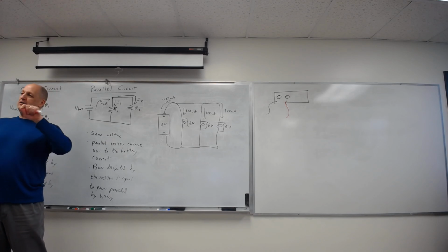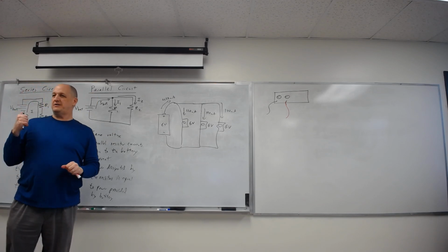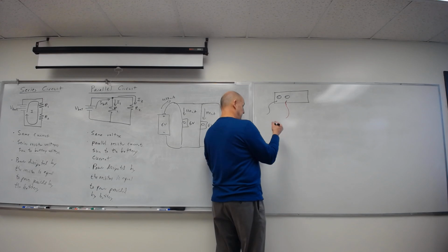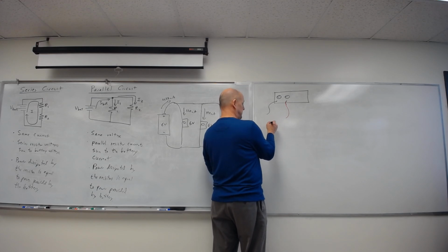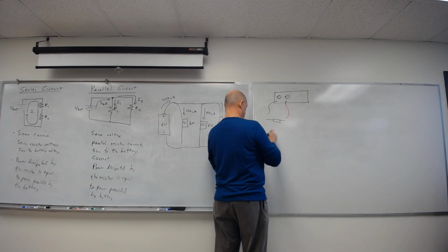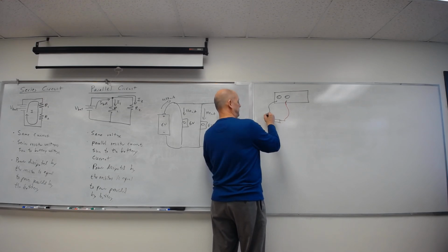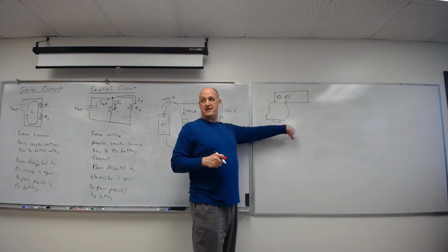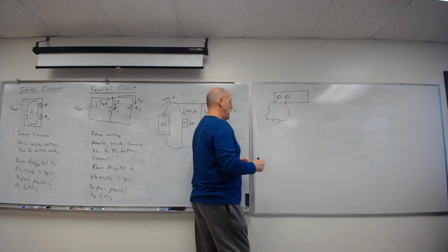Don't connect power through my ammeter directly to the ground to measure the current. You have to have the resistor in there. So if I want to come down and do a single resistor, the first part, I just put that resistor in here initially and connect it. So I have a circuit. It's my brown, black, red resistor, 1 kilo ohm, that I passed out the other day to everybody. How do I do it?